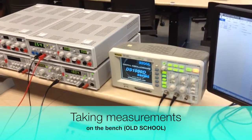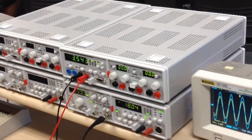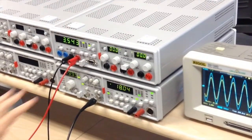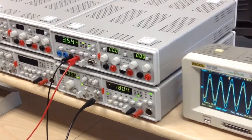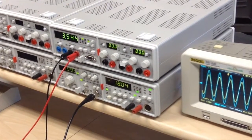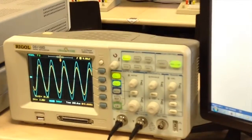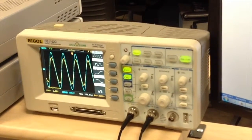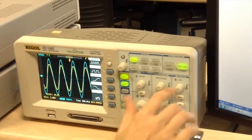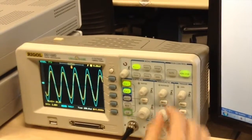So we already have our RMS voltage across the circuit, right? It's right over here. We figured that out when we calibrated it, and it's roughly about the same once we have everything connected with our resistors. Now we're going to measure the voltage peak to peak using the oscilloscope, and we're going to start with the old school method. For the old school method, we start off with an auto. It gives us a good start in terms of having all the scales where we want them to be. Let's turn this menu off.